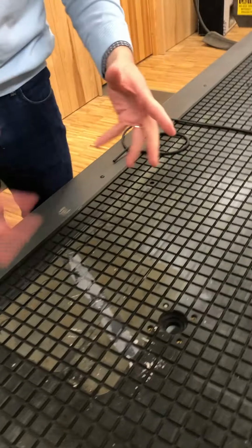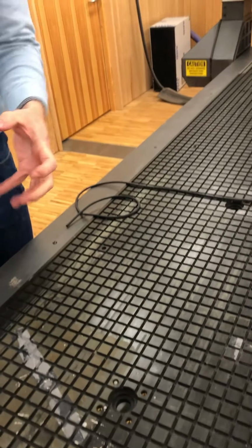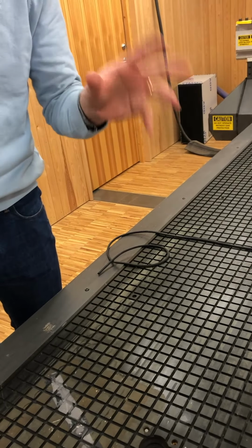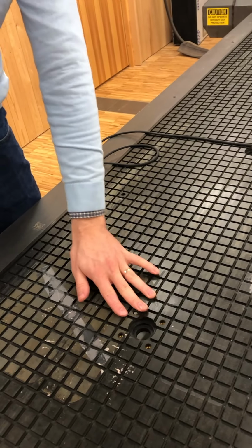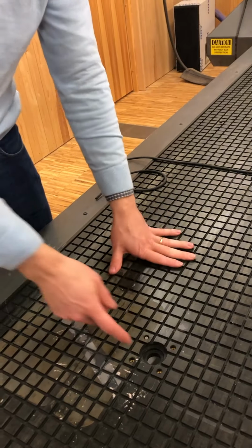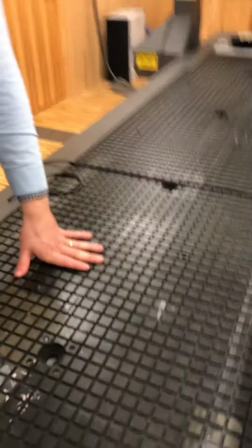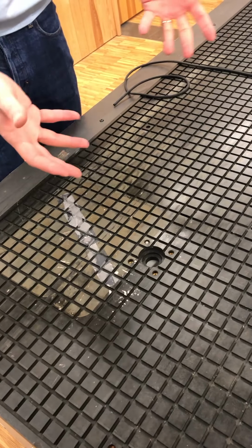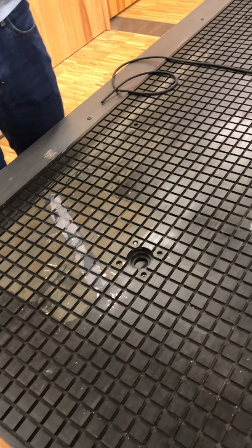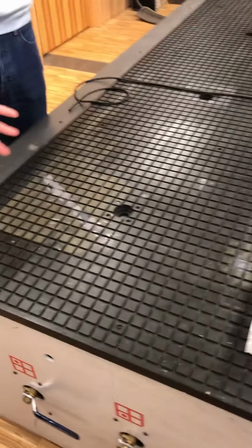Because the vacuum suction system is not perfect, it has some leaks, and one can fix or diminish those leaks by having material which covers this, like small thin cylinders, which usually there were, for each hole here, a metal one. But they get very easily sucked up in the vacuum when you are done with the machining and you are cleaning up.